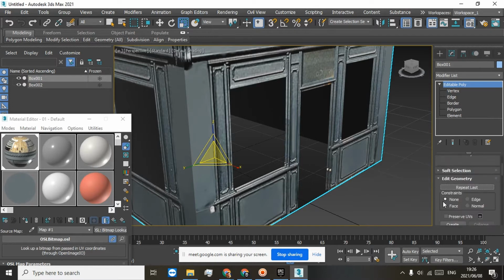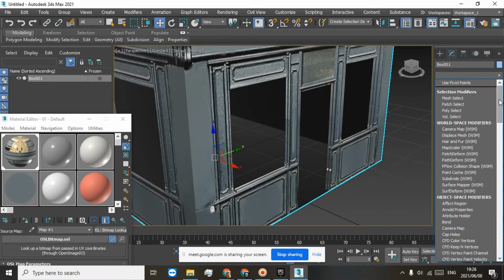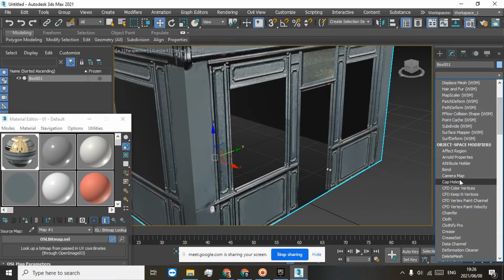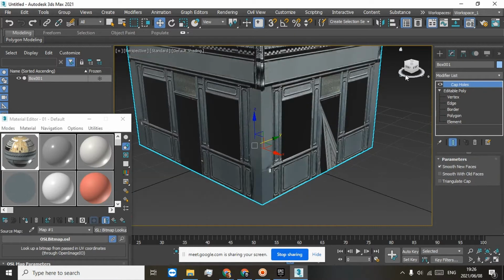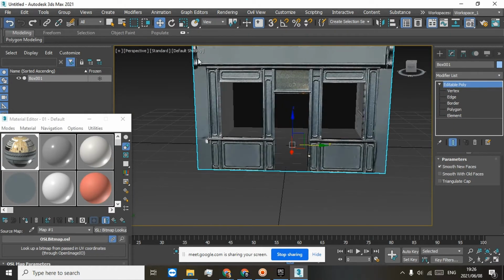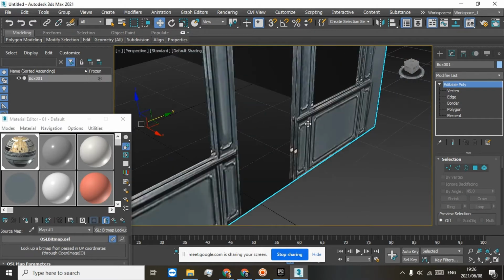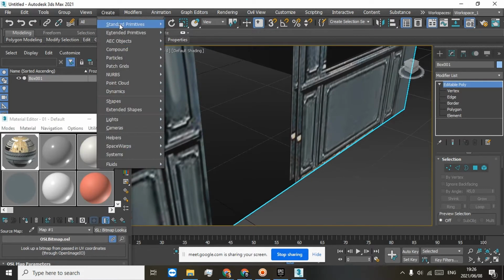Okay, there's a few ways of doing it. Let me quickly try. I want to attach it to that one, so it's one singular mesh. I still need to invert those inside verts, but try and cap holes. Oh no, it's not going to work because I'm capping my own holes I created. Okay, other way around. Easiest thing to do is create a plane.